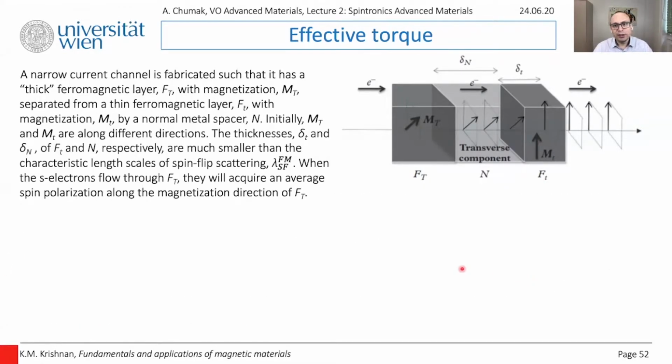Okay, let us now introduce the parameters with which we are working. So what are these indexes? T large stands here for the thick ferromagnetic layer. Why should it be thick? The idea is that we want to create a situation where the magnetization of this layer is fixed, so we cannot change it when we send current in one or another direction. So we want to have it really like a spin polarizer and to stay in the same configuration always. And the easiest way to do it is to just make it thick, and then it will be stable there.